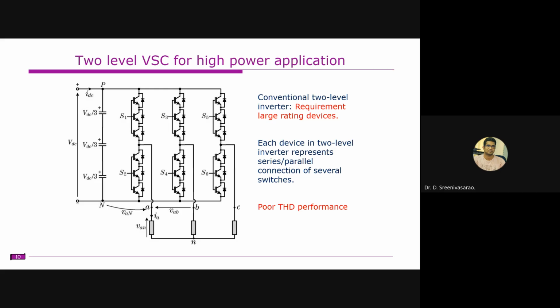The drawback with this one is that the number of switching devices is higher, but from the performance point of view, it is still like a two-level inverter. Obviously, if you're designing a filter like an LC filter for a huge voltage like 11 kV, the size of the inductors, capacitors, and their isolation will be much bigger, and it also costs size as well as weight. So these are the drawbacks.